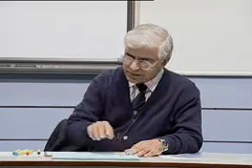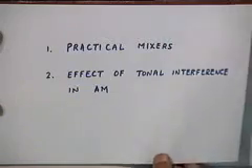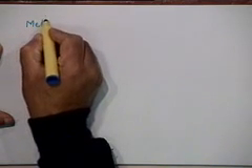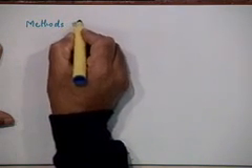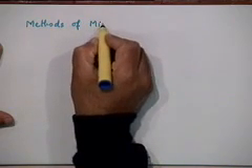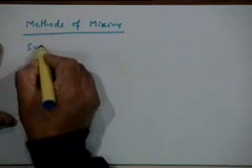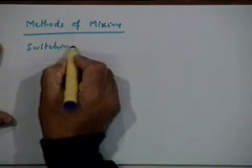The second kind of mixers that we can have is based on the switching principle, which also I believe you have some idea of, and we will just quickly first review what you might already know. So we are looking at some methods of heterodyning today, or mixing. And in particular we look at first the switching modulator, which is very simple.